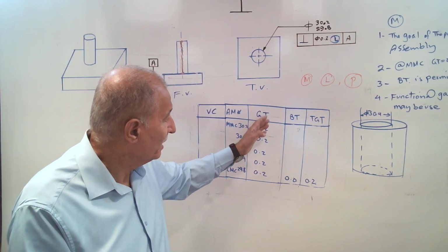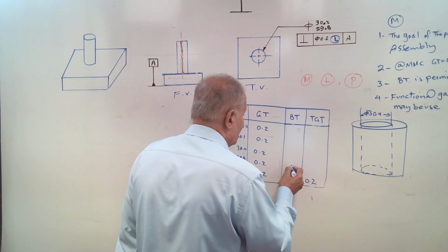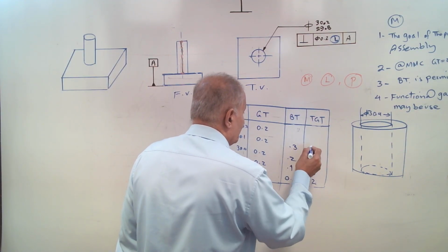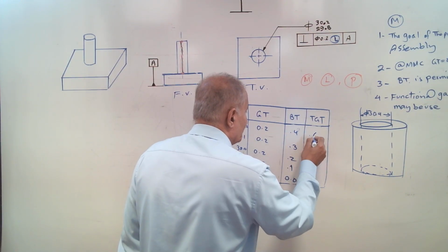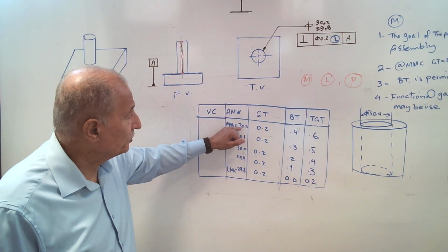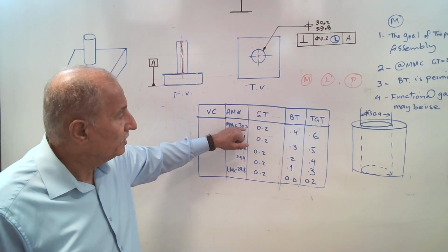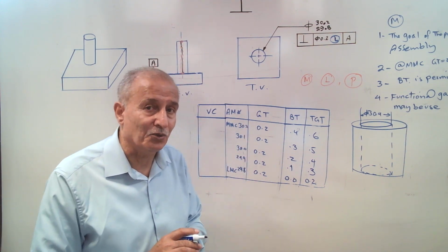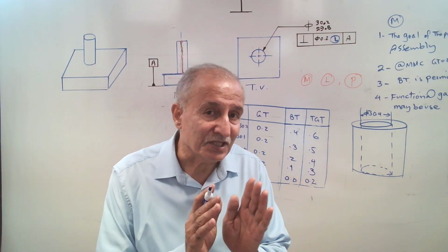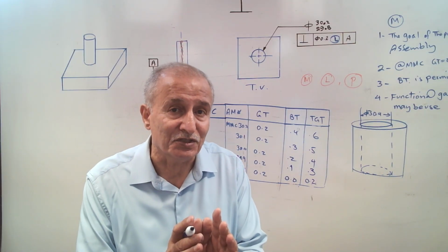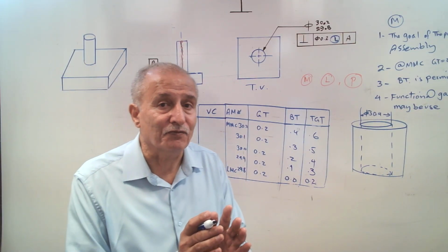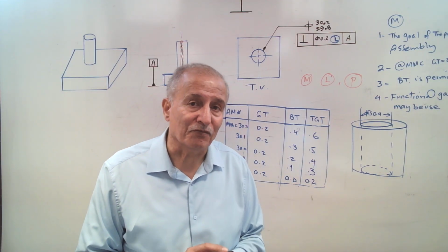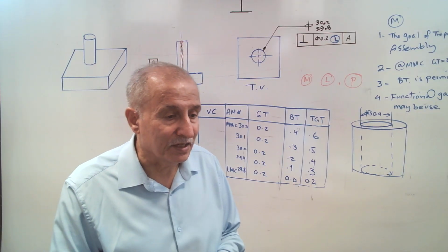This is why the table is different. This is point actually 1, it should be 0.3, this is 0.2, 0.4, this is 0.3, 0.5, this is 0.4, 0.6. It means that manufacturer, if you produce at 30.2, you can have 0.6 error. Since if we remove 0.6 error to fix it, for example, still there is sufficient material inside this shaft that protects it from fracture. We talk about this L modifier and everything else in the other video.